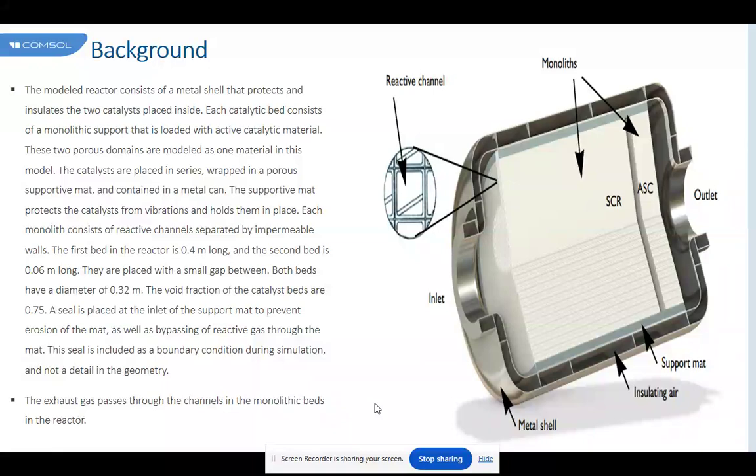However, this simulation has demonstrated with a theoretical model that a combination of cell densities in a single monolith can lead to a conversion efficiency lower than that obtained when using either of the two cell densities alone. Let us refer to that as unbounded efficiency. The aforementioned result can be considered a negative one since what is desired is a higher conversion efficiency. Nevertheless, it shows that unbounded efficiencies are possible when combining cell densities.